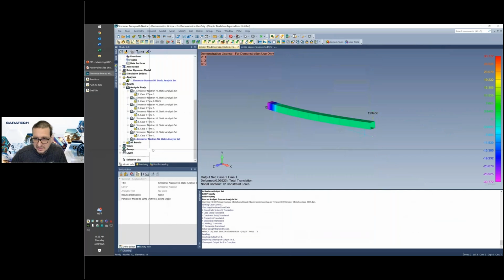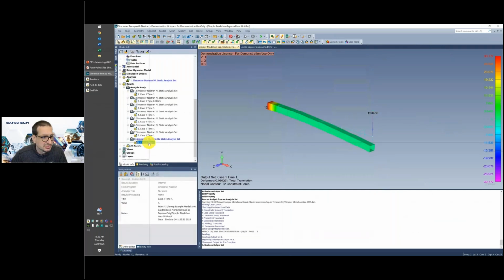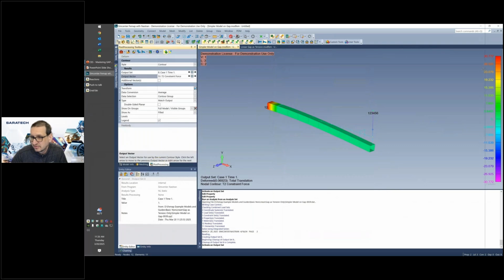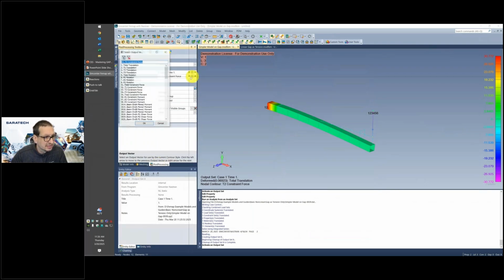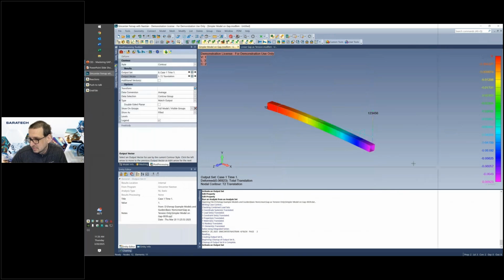We should basically see the same deflection, just in reverse. And we can see the reversal of the forces, 30, -30 here. We can go back here, look at our T2 translation, and see, yep, it's basically compressive. It just pushed it away as if it had that preload force. So with solution 106, you can use either or.